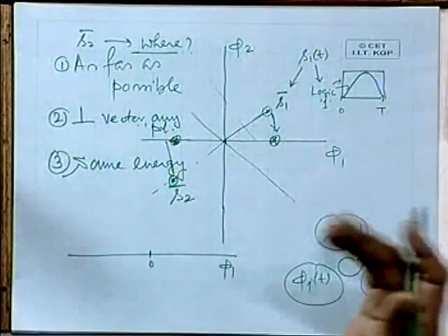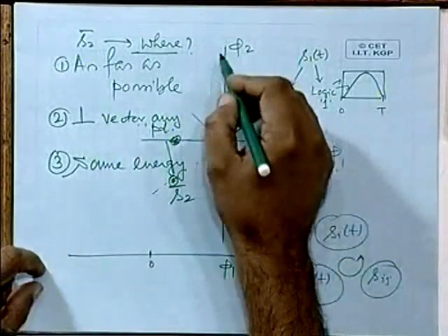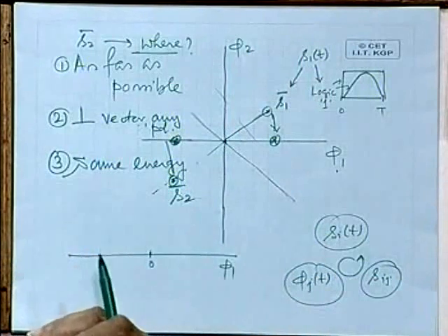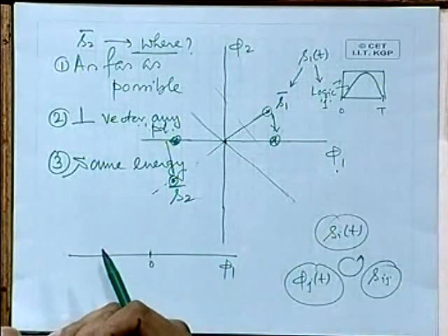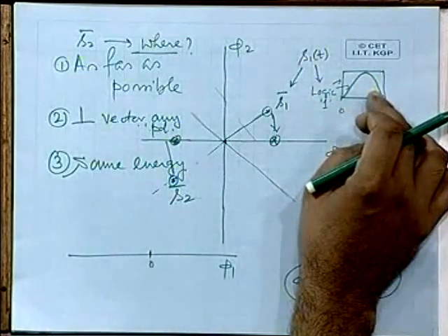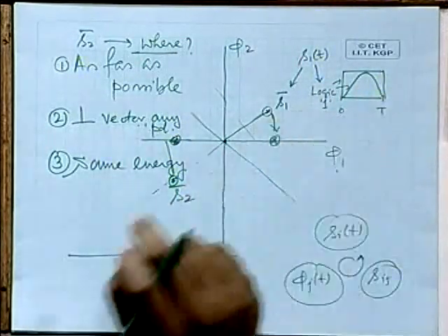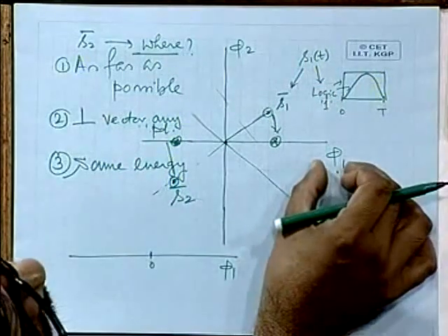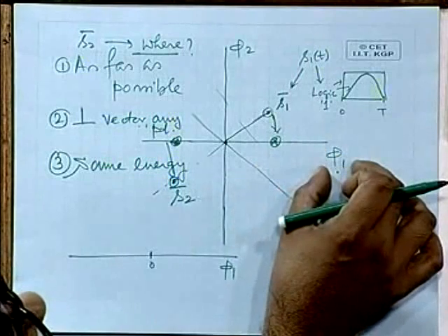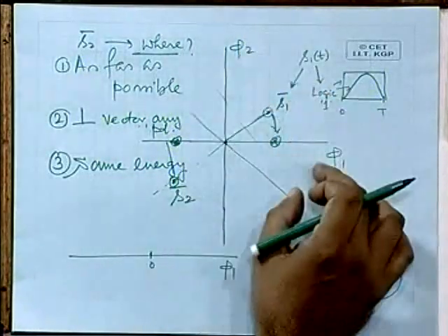This description is valid for both baseband low pass equivalent signals as well as carrier modulated signals. The connotation of phase is easily understood when you talk about a carrier modulated signal, where, for example, for a two dimensional signal space, the usual basis functions that can be taken are cos omega c t and sin omega c t over the time interval 0 to T, along with the corresponding baseband signal, so that the signal energy is also maintained. Now, this cos of omega c t with unit energy is viewed as one basis function phi 1, and the other one is sine.